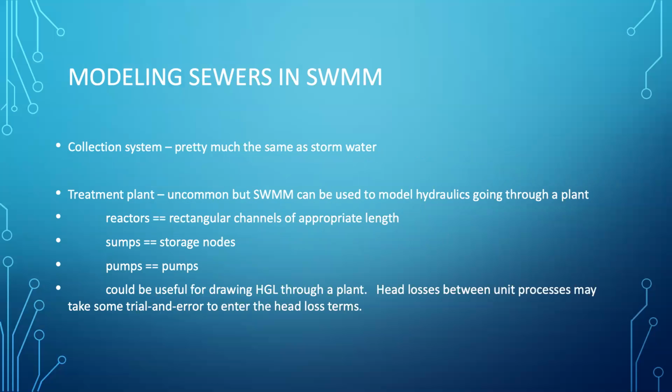So when we get to the point of having to do the hydraulic modeling, we already know how, because the collection system pretty much works the same way as a stormwater system. We can actually model it in SWMM. And SWMM, in my opinion, would be as good a modeling tool as any for checking the hydraulics of wastewater. Because the flows are actually somewhat confined, SWMM may even be overkill.